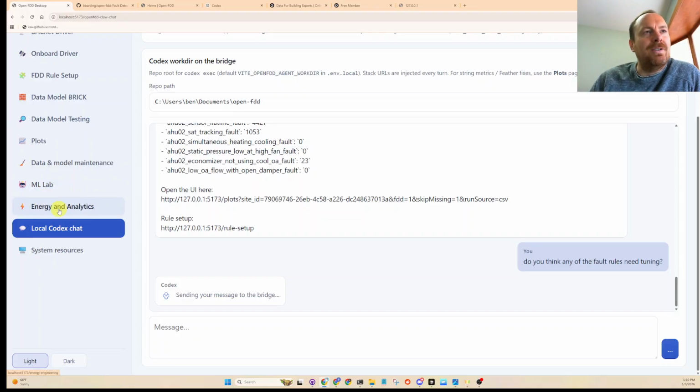And then perhaps maybe some of this energy analytics could be something too, where I think a lot of these fault detection platforms have some component of, if it is a fault causing a really big energy penalty for the building, that you can calculate the elapsed kilowatt hours or units of gas in therms, and then someone can equate that to a dollar figure.